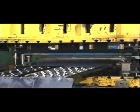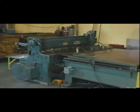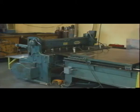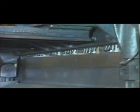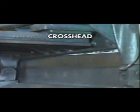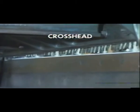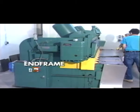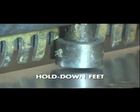Sheet metal shearing can be done with a shearing die and a stamping press, but is most often performed using a machine called a shear. A typical shear consists of a fixed lower blade mounted on the table or bed of the machine, and an upper blade secured onto a vertically movable crosshead. Other shear elements include the housing or end frame and the hold-down feet, which secure the sheet metal or plate stock to the table to prevent movement during the shearing operation.